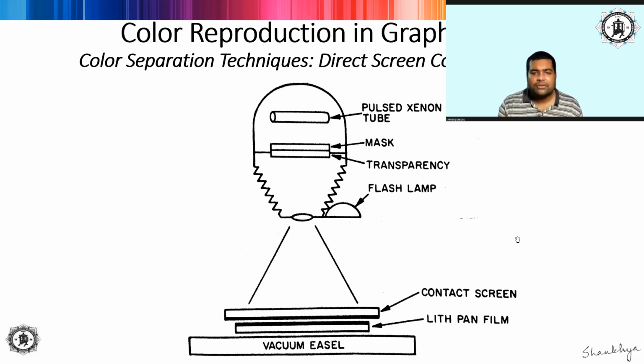As we know, because we are processing in an automatic processor, the film needs to pass through multiple rollers, which wash off the unexposed areas and apply the developer solution, so that during that abrasion no visible lines are formed onto the masks, which may ultimately be transferred onto the reproduction, and that is unwanted.